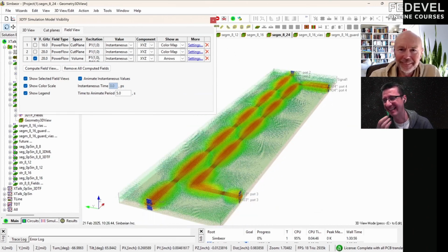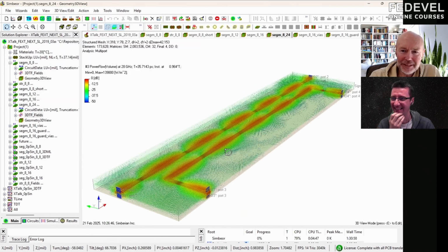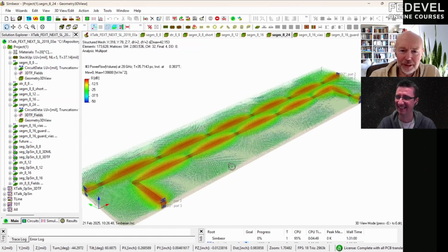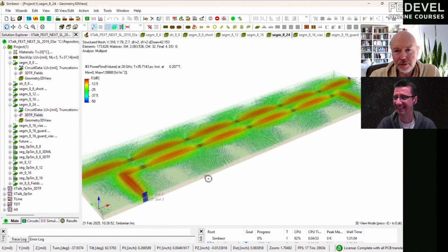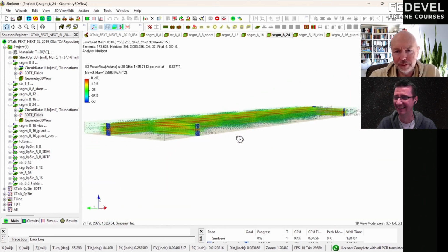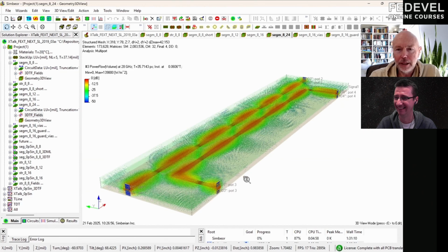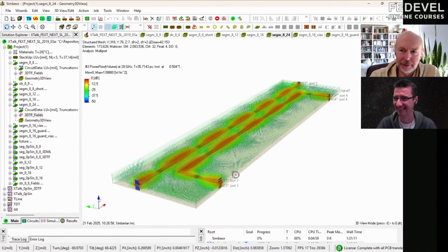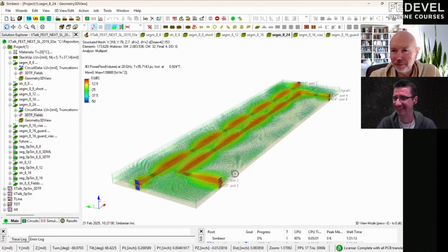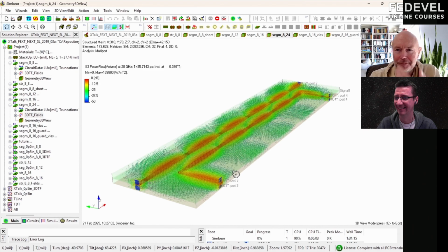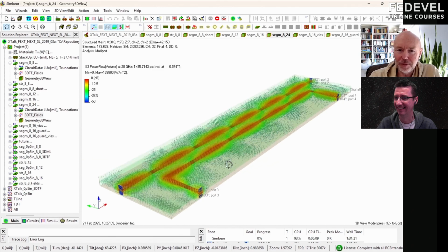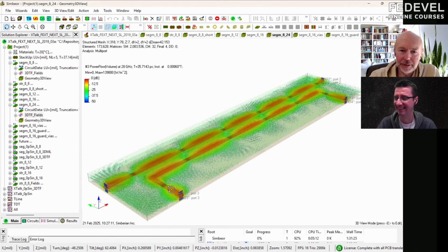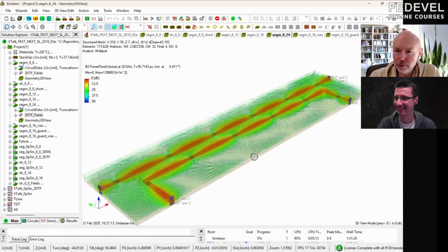Yeah, this is really messy. It's really messy, and I put it down to minus 50 dB. And that's how messy it's going to be on a real board in a stripline configuration if you don't get something done about it. And we'll take a look at what can be done about it to reduce it, and we will take a look at the signal propagating in both directions. So they are both getting some amount of crosstalk here.